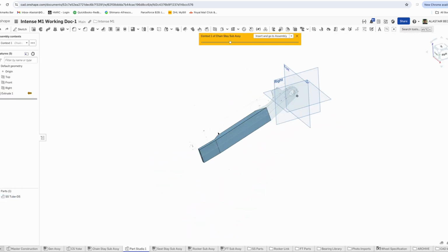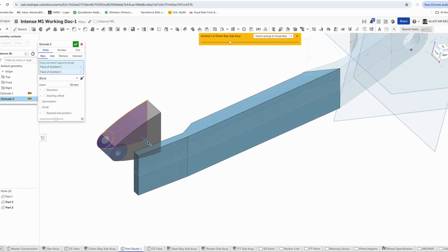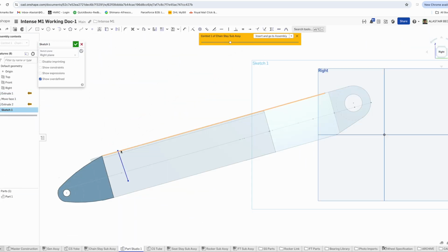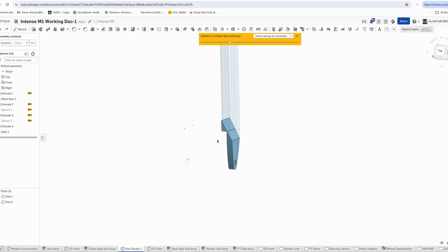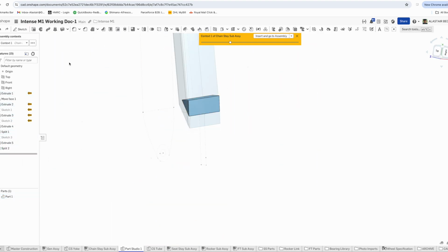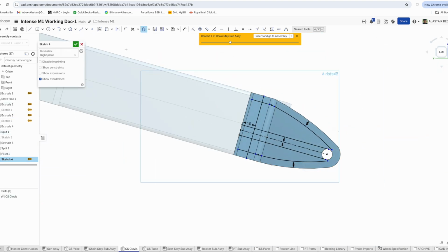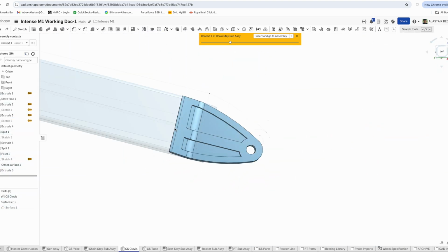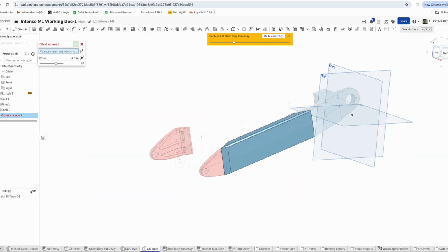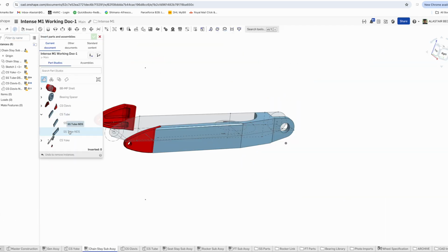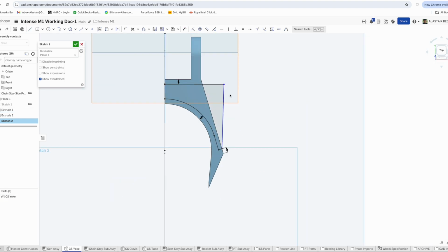So here I'm extruding the tube out itself, putting some miters in there, because I can at this stage. We've got the sketch, and then these dropouts, which are a bit tricky. I had to go back and forward a little bit, because getting details off the photographs that I had was hard. But you could see that there was some sort of angled contact or interface there for the weld. So I got there eventually, and then essentially pocketed the back of this dropout clevis part. I'm not sure what it's called. And then we're going to start mitering everything to suit. So the tube's got a bit of a miter. Again, probably not super accurate, but based off the photo we had, it was not terrible.